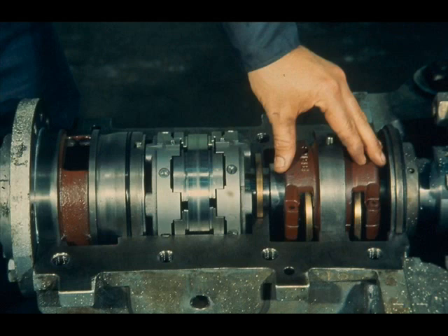This bearing is of the split sleeve type. Your prior instruction should have familiarized you with this bearing and we will not deal with it here. Note that it is compartmented with the bearing housing and is lubricated with oil rings. Lubricant for the sleeve bearing is supplied by the system lubricating the thrust bearing.